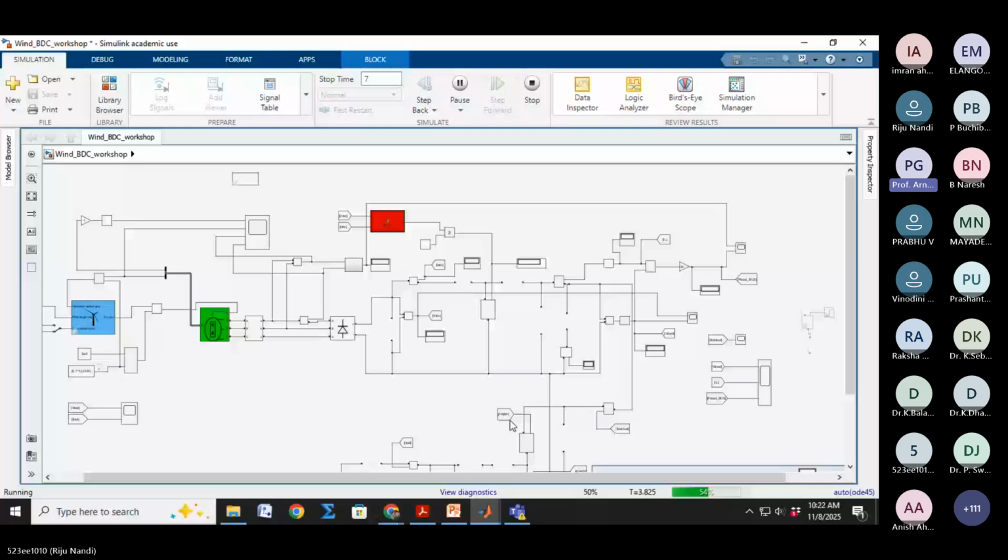If we go for the classical controller, we need to get the plant transfer function, that is, the converter output to control input transfer function. From there, we can design the classical controller, everything on the linear platform. Now, if you go for non-linear controller designing, suppose sliding mode controller designing or bang-bang controller designing, in that case, what happens?